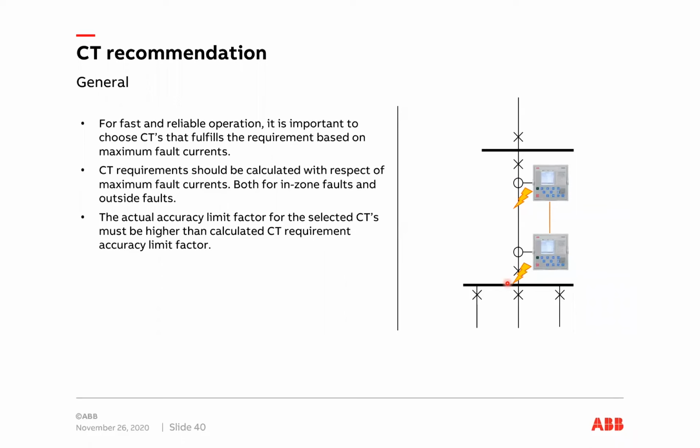And this must then be compared to the actual accuracy limit factor for the CTs that we are planning to use. So the goal here is that the actual accuracy limit factor for the CTs must be higher than the requirements.